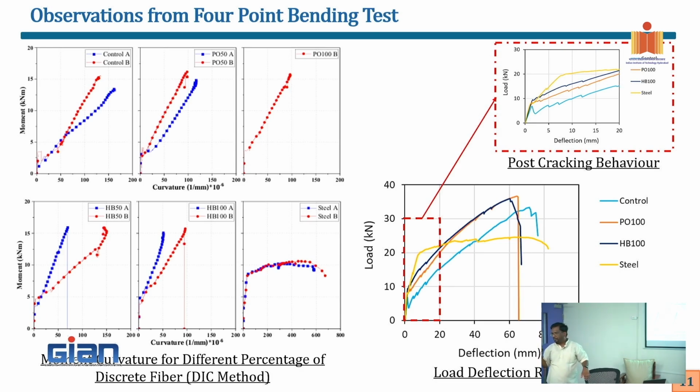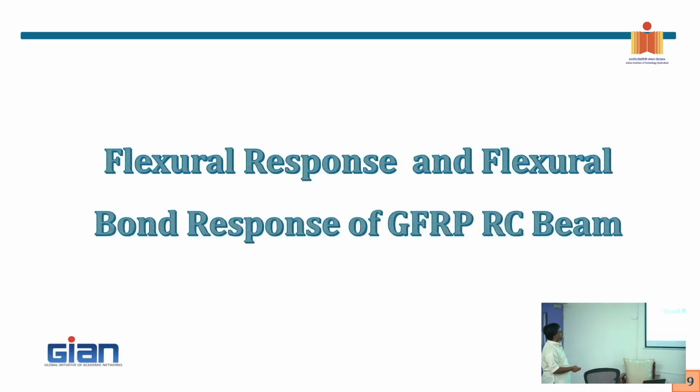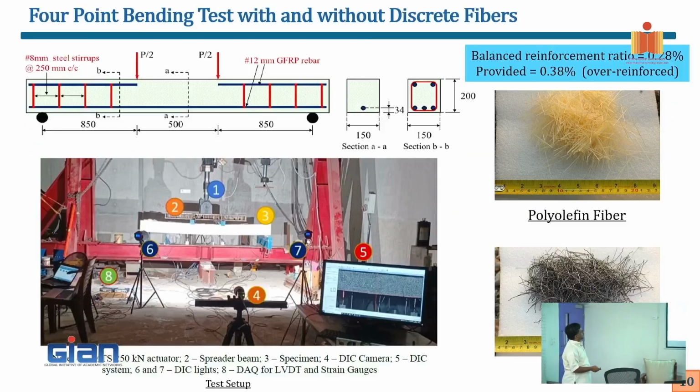But still we need MCR for calculation, because I need to know how far I am from M cracking. Let's say my service moment, right? M cracking, let's say in this example, what is the cracking moment that you have? Roughly about, let's say 10, okay, maybe let's talk in terms of kilonewton meter, right?